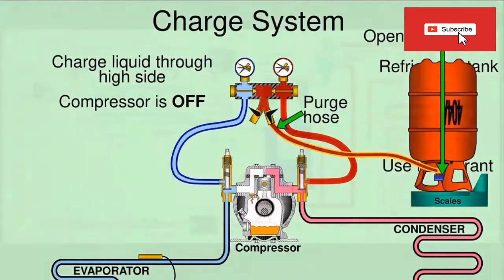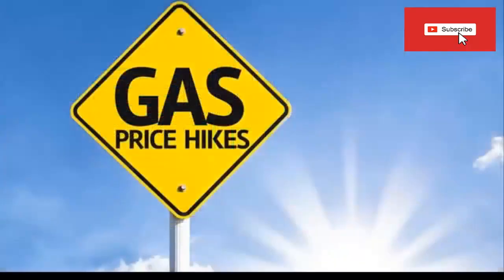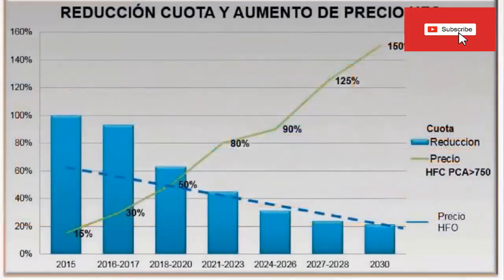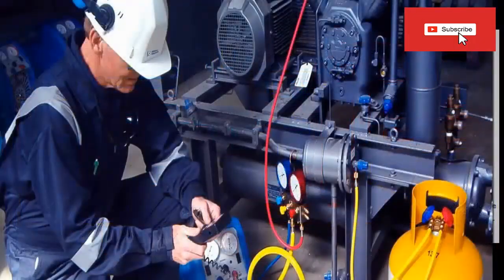Remember that R404A refrigerant is already prohibited in many new refrigeration equipment, and only recycled refrigerants can be used for service. This has caused R404A to gradually disappear from the market in many countries, and has also caused a sustained increase in its price. For this reason, and some others, the refrigerant change will be carried out in the equipment.